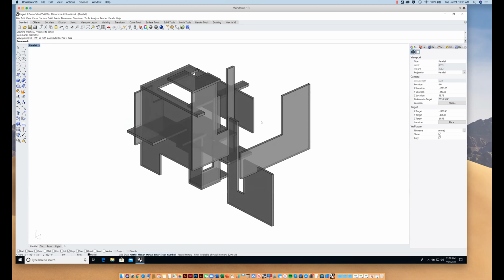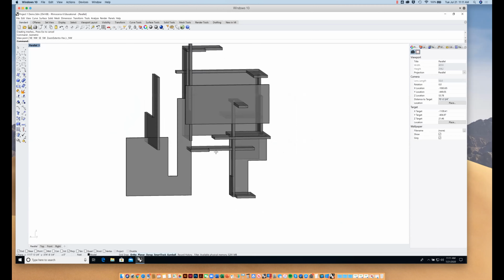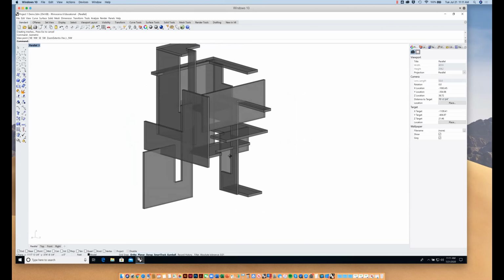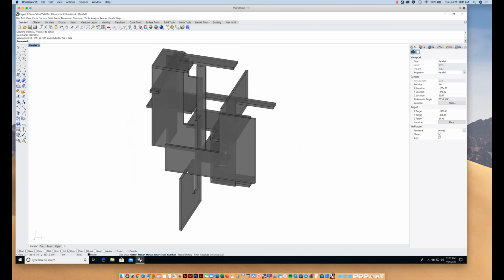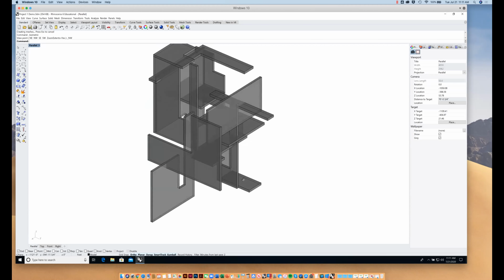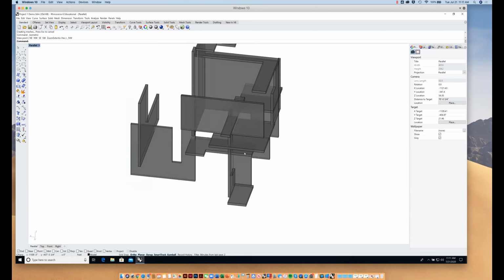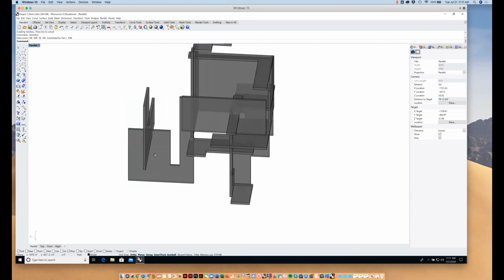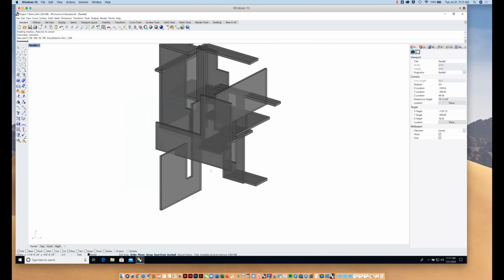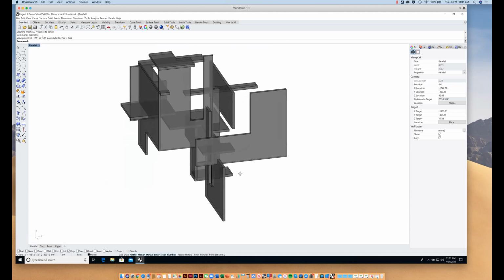There's a couple of things that I wasn't really paying much attention to when I just did this in Rhino, like gravity. So I have this ridiculous situation where this is cantilevering outwards and there's nothing that it's resting on. What I can begin to do is think about where I would add glazing or glass or windows or curtain wall. And I can model that with just a simple surface. I'm going to do that instead of drawing these out flat on the XY plane and then tilting them up and moving them into place like you did before. We have a working model, so I'm going to try to draw some curves or snap to certain edges and corners and make surfaces for the glass here inside, three-dimensionally, okay?